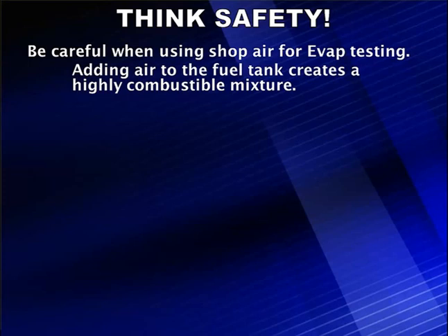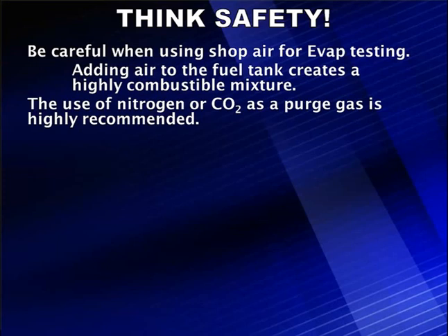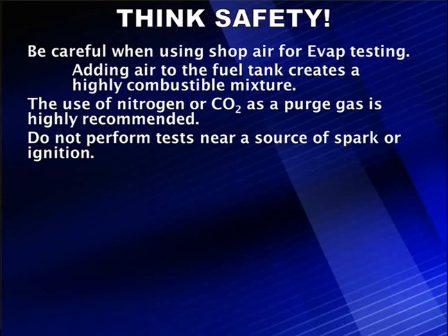Flammable means you've got a fuel. You give it air, you give it a spark, then you can have a fire. We're beyond flammable. So most vehicle manufacturers recommend the use of nitrogen or CO2 as a purge gas. Now that is much safer because neither one will create a combustible mixture. Remember, you're pumping this stuff out. You're pumping out hydrocarbons that are combustible.